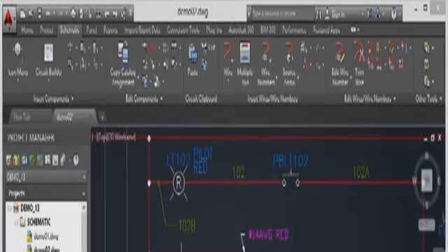To see the wood for the trees sometimes in your AutoCAD electrical drawings, you do need to hide some of your component attributes, purely because there's just not enough space on a drawing occasionally. We're still in the Demo 13 project. We're still in Drawing Demo 02. What we're going to look at is hiding attributes on components.